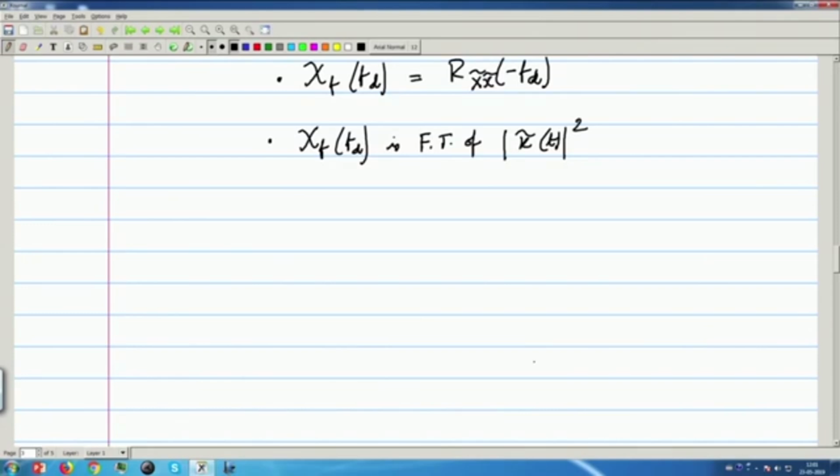As I discussed in the last class, the ambiguity function should be peaky at 0, whether in tau or in f d, and should come down very close to it, so the roll off should be high. People generally do not take the null; they take, let us say, 3 dB.